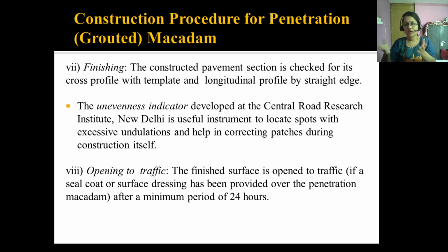And then opening to traffic: the finished surface is opened to traffic, if the seal coat or surface dressing has been provided over the penetration macadam, after a minimum period of 24 hours. So with this, I come to the end of this lecture.